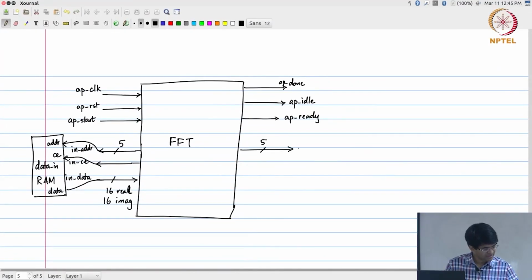Right. So, once again a 5-bit out address, chip enable and write enable, right. Maybe not strictly speaking necessary, you do not need to have two such signals, but this is normally done for writing anyway. You have one thing to activate the memory and the other one to say I am writing into it.